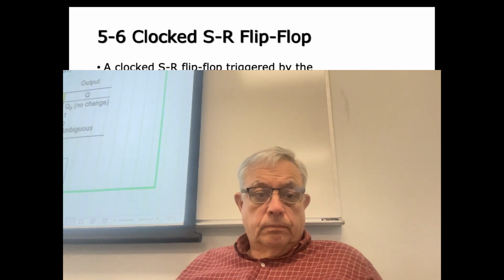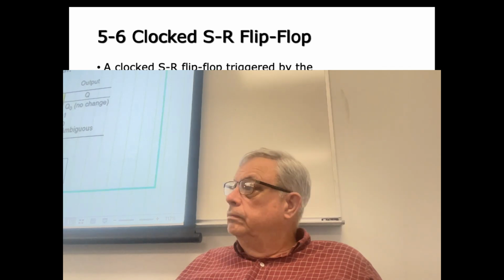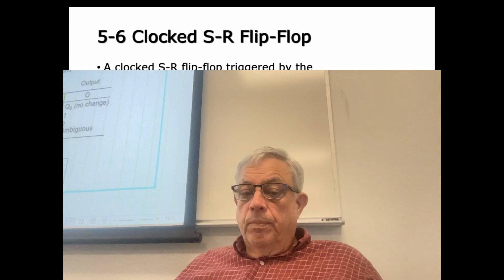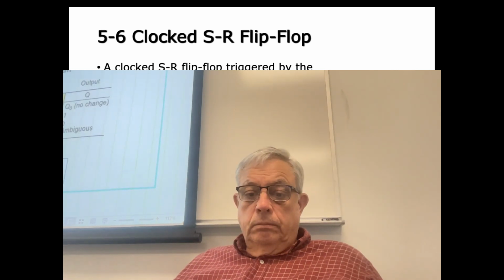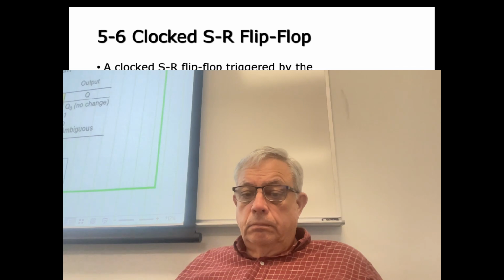That obviously determines if the clock is going down or up. You're looking for the bubble. If it has the bubble, it's going down. If not, then it's going up.